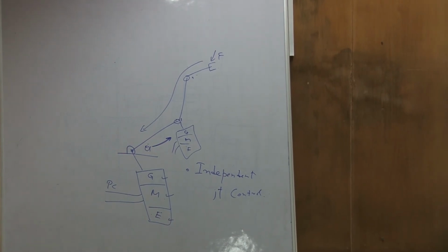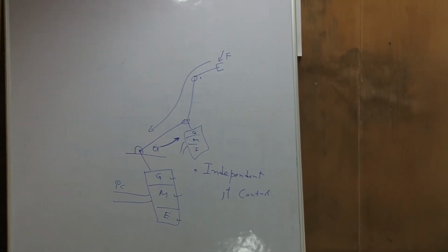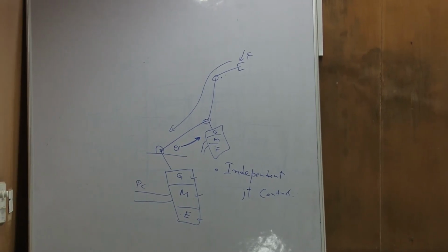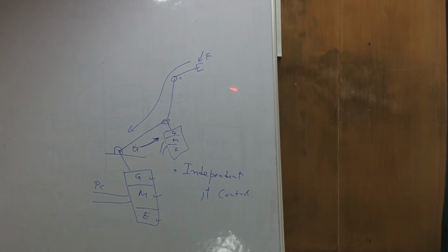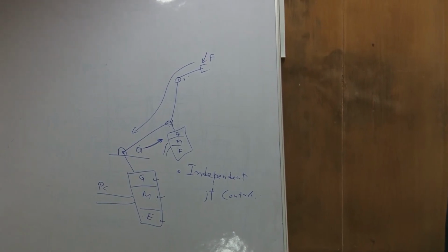So, internal sensor is required for the basic working of the system like position, velocity, acceleration. And then there are, so without these internal sensors, the robot cannot work. Without internal sensor, it cannot work. Now, there are also sensors which are external sensors. For example, there can be a force torque sensor there, there can be a camera mounted there. Now, these are external sensors. So, external sensors are required for interaction with the environment. For example, vision, force torque. Now, if some of this goes bad, the robot will not die, but it will still work, but the interaction with the environment will come down.